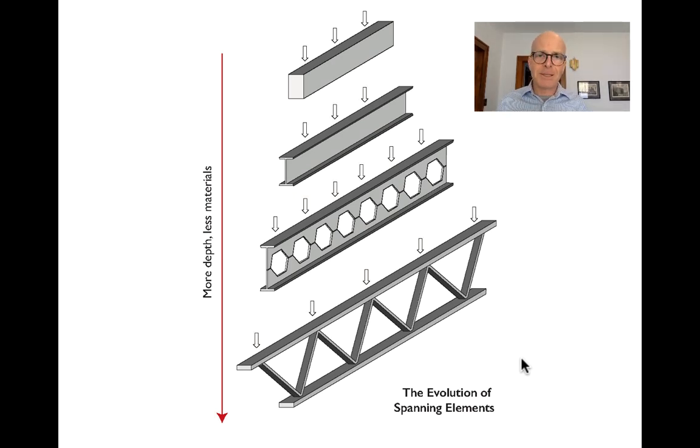When we go to castellated beams or we go to trusses, we're saving on material, we're gaining performance. The sacrifice is twofold. These are all going to be much deeper than if we just have a standard beam, so we're losing a bit of head space. And we're also spending more money on fabrication, right? We're doing more in the shop to create these more complex bending shapes.